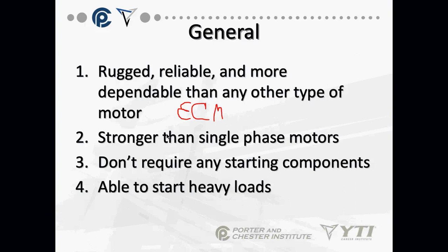It takes the AC current and changes it to DC by the time it gets to the motor. So my statement about being more dependable and reliable than any other type of motor excludes ECM motors, which we're starting to see in a lot of residential equipment. ECM motors are awesome because they're DC motors, and DC motors last a long time. So just be aware that my statement excludes ECM motors. That's a whole separate conversation.